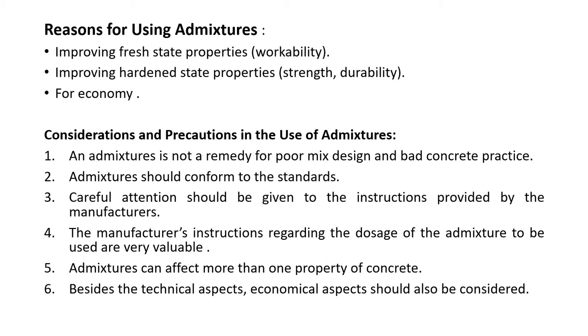Considerations and precautions in use of admixtures. An admixture is not a remedy for poor mix design and bad concrete practice. Admixtures should conform to the standards. Careful attention should be given to the instructions provided by manufacturers. The manufacturer's instructions regarding the dosage of the admixtures to be used are very valuable.